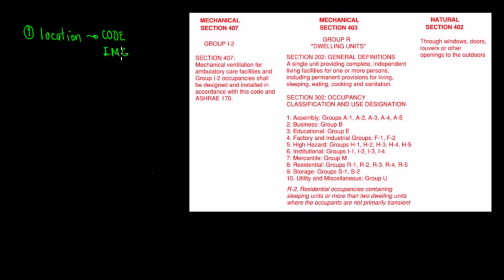So the question is, why do we ventilate? Why is ventilation very important? Because when we're doing HVAC design, for residential or commercial, one of the first steps is to do ventilation calculations, right? Ventilation calculation, and then after that we do the heat load calculation.